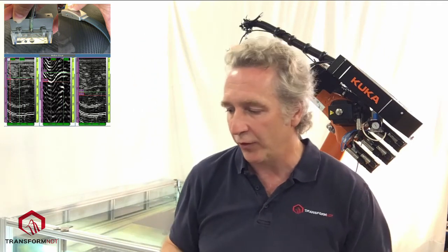So at the moment, here today, we're using manual measurement of waviness, using rigid or flexible arrays, where the operator manipulates the probe to get a good image of what's going on inside the laminate, and then uses manual cursors to position those on the wrinkles and extract the information that the stress and design engineers might wish to know about the waviness.